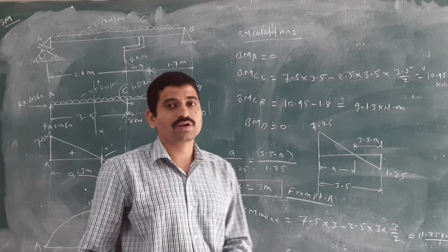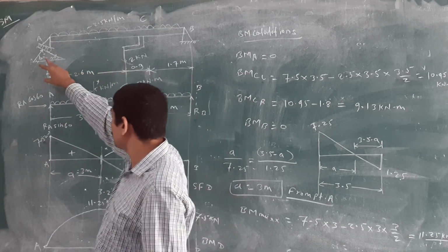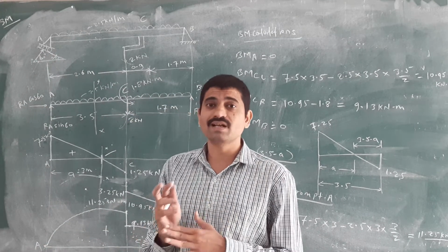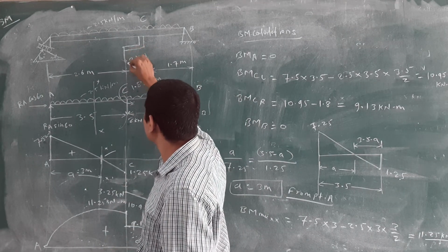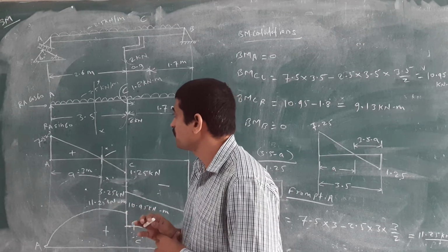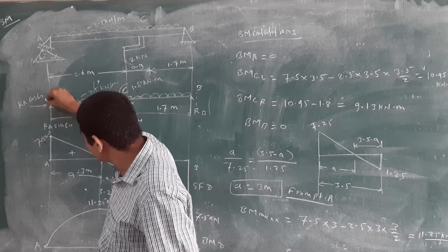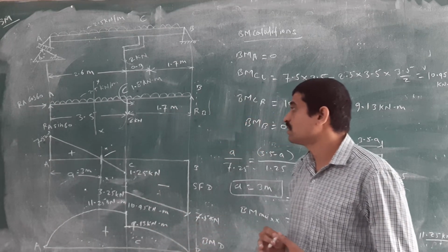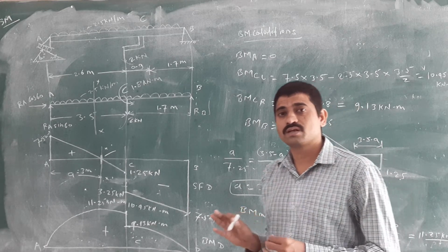Okay. Here the important thing is, if you have been given a point type of load or you have been given the roller support in an inclined direction, then how to convert it to the vertical direction, also how to convert that point type of load into the moment or couple. Remember that. Okay, are you getting how to convert this RA cos 60? We are not using the horizontal value because they have not told us to calculate the thrust diagram. Okay, this is not given in your syllabus.